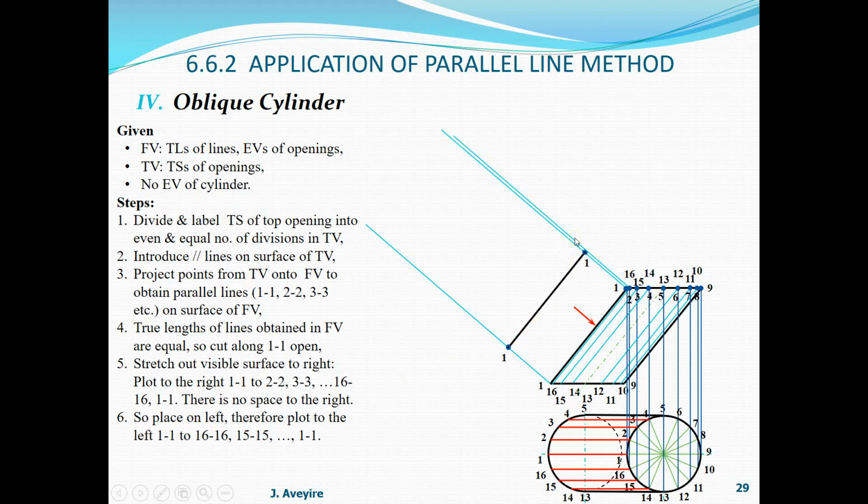What is the point? This time it's not a perpendicular distance. We don't have the perpendicular distance between the lines, but instead we have the distances between the points, which are the arc lengths over here. These arc lengths are equal to the radius. So we come to point 1 and prescribe an arc over here, and that will hit the line to give us our point 16.